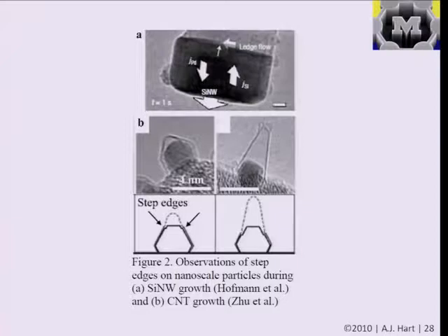And you have to cross a nucleation threshold every time a new layer is created, and then it grows, and then another layer nucleates, and the next layer grows across. And in the case of carbon nanotubes, what's being seen in most recent studies at the atomic level of the process is that atomic steps between the catalyst nanoparticle and the structure are important in essentially attaching the carbon to the particle.